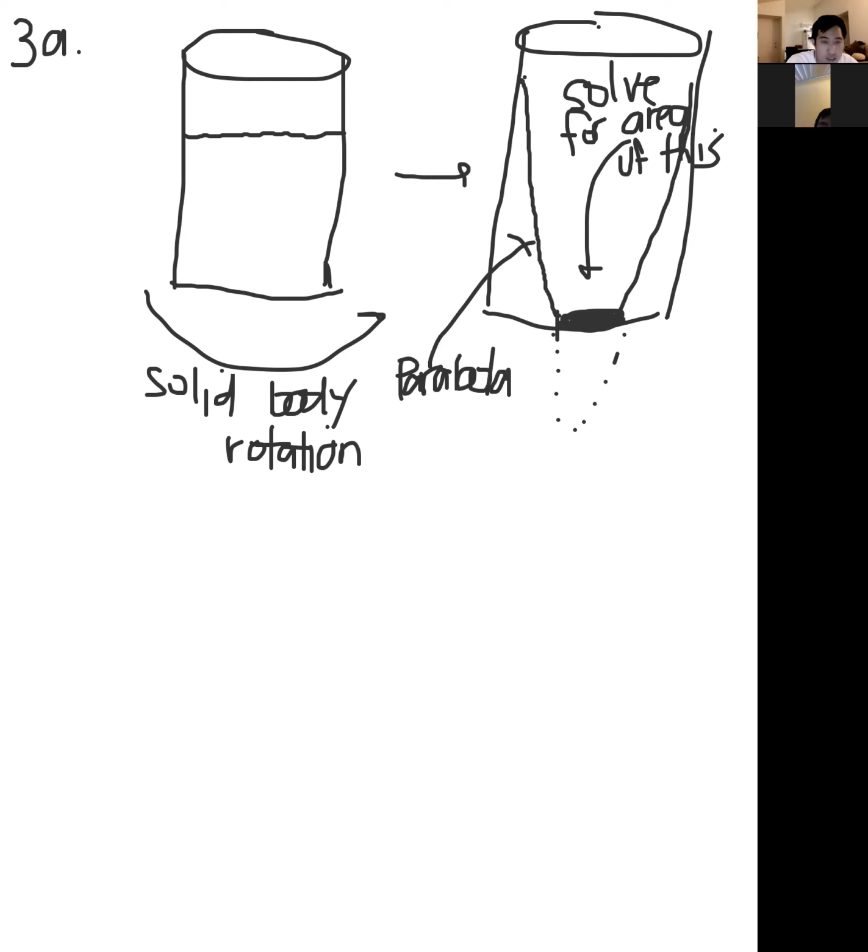To do that, it's a little bit tricky, because in the notes, which I have right here, what I gave you was a formula for the pressure for z. So from the notes, if we have solid body rotation, then the curve for the free surface is given by this formula. We have z is equal to omega squared r squared all over 2g. And it's subtracted by some other stuff, but we can assume that other stuff is going to be 0, so we're going to just ignore that.